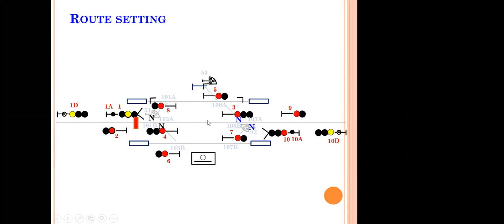So we are guided by some rules called the General Rules and Subsidiary Rules of Indian Railway, where the reception signals have to be ensured with the overlaps. No other signals are necessary. That is the reason we are not ensuring. If the overlap is not ensured, the signal cannot assume an off aspect, that is, a caution aspect.